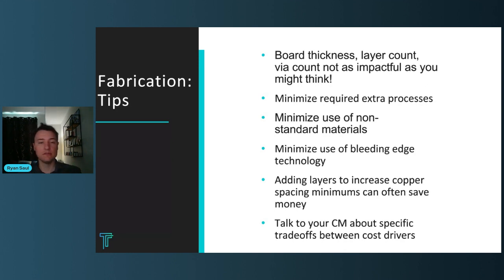Maybe instead double your layer count and use 2-ounce copper, or quadruple your layer count and use 1-ounce copper and run everything in parallel. I know this is not an appropriate solution for all designs, but in many cases, you leave your board with similar or superior current carrying capacity and thermal mass, and it's so much easier and less expensive to fabricate.